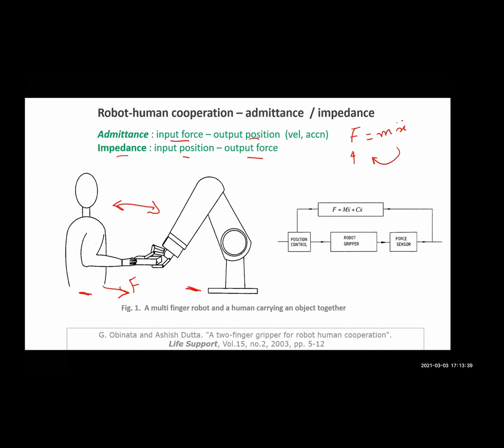Now, the control system in the robot is actually a PD controller, which is basically a position controller. What is a position controller? It determines an error, E desired minus E present, then puts a KP and a KD on that error E, and controls in the position domain. Whereas the human being is basically an impedance controller. So there is a mismatch here. What kind of mismatch?